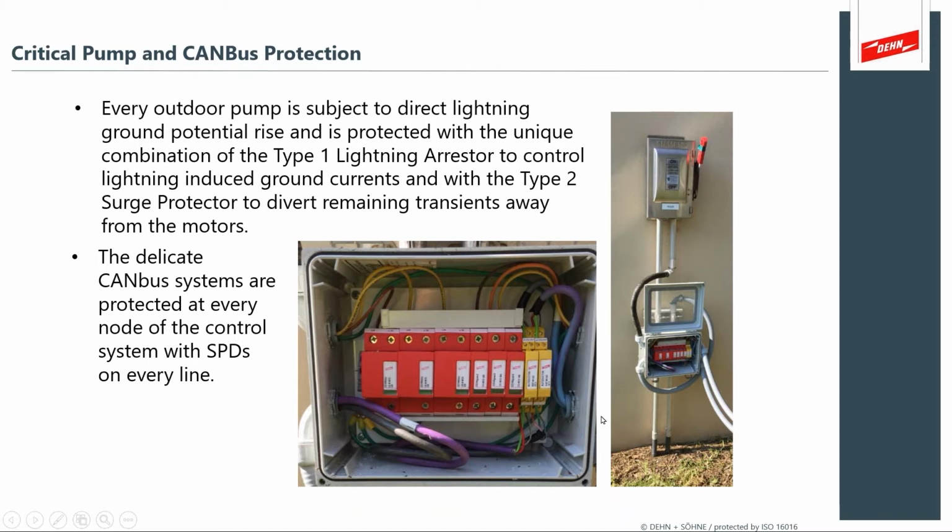And here in this photograph, we see the data protection for that pump system at these point of use applications. And that's why it's important to apply the SPDs on both ends of that CAN bus data control system.